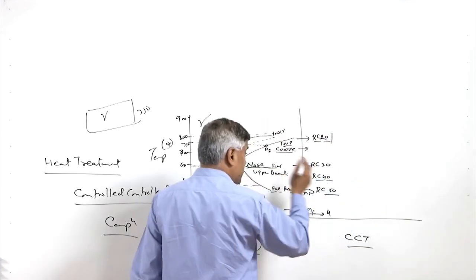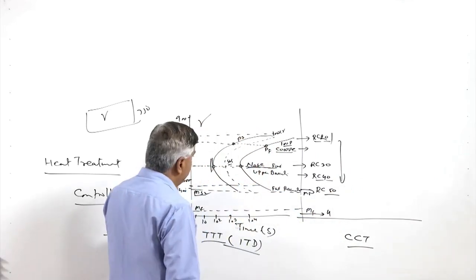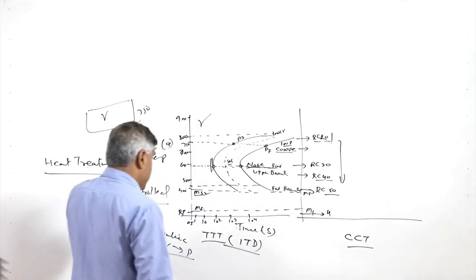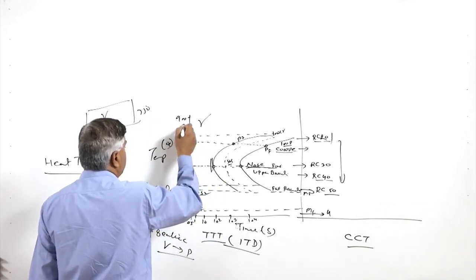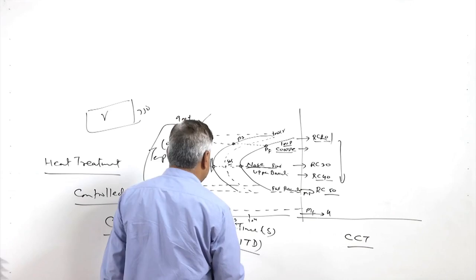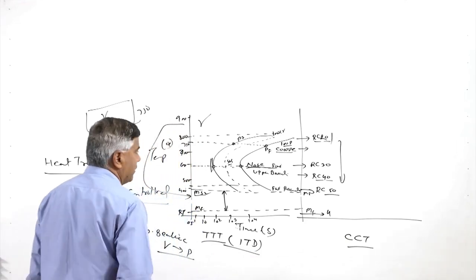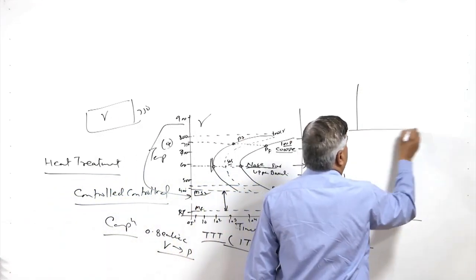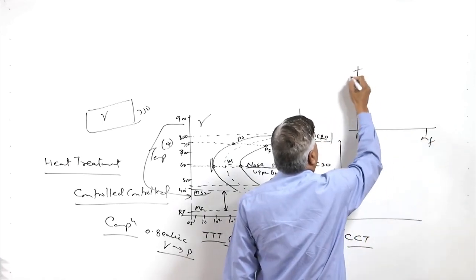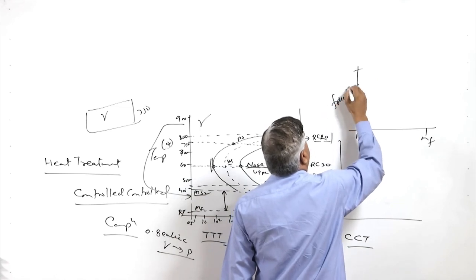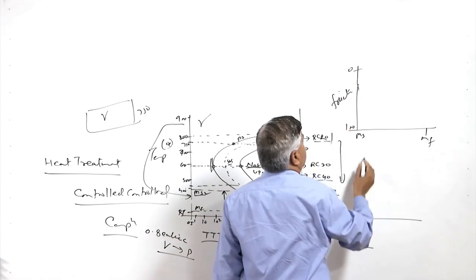So, the hardness increases with the change of the phases being formed at the constant temperature. And if we quench directly from 900 degrees centigrade to a lower temperature, martensite is formed. How the martensite forms as a function of time is what we can see here, with the MS temperature and MF temperature, and the fraction of martensite being formed, from 0 fraction to 100% fraction.